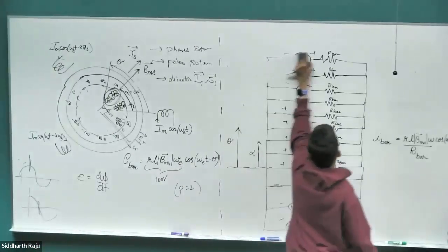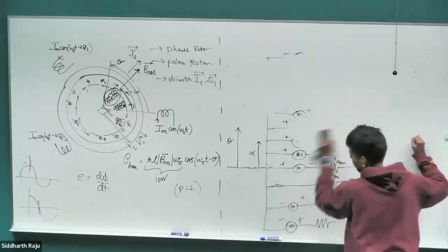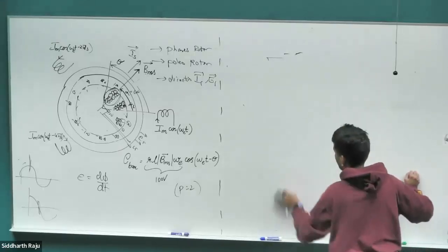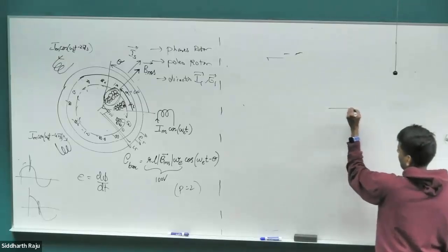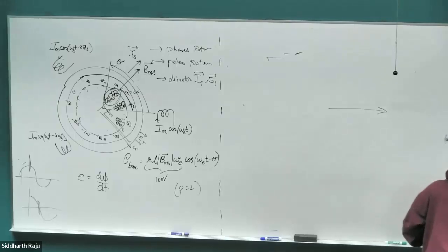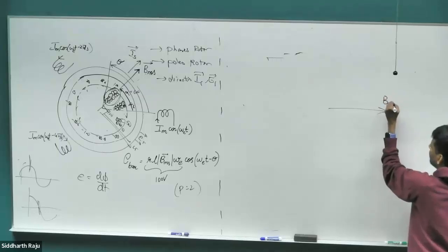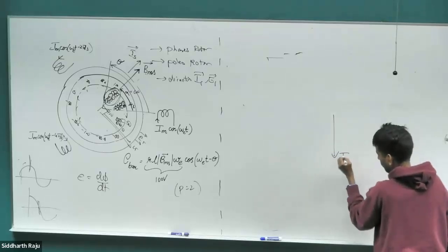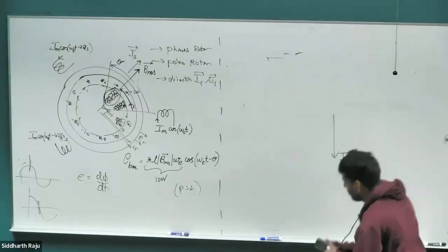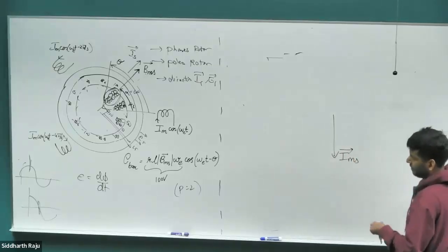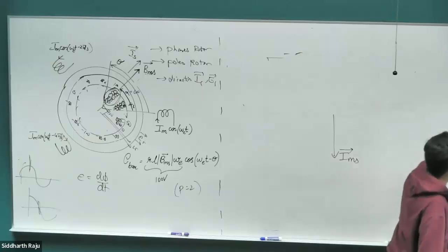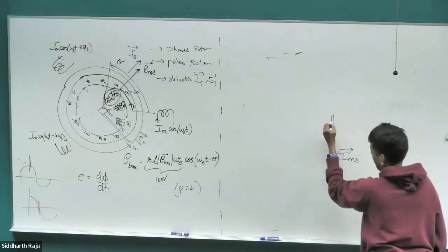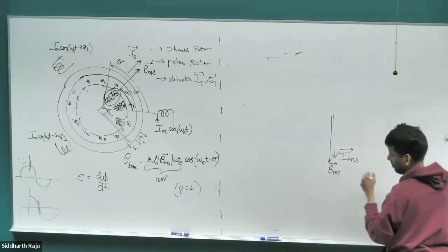So let's come back to our induction motor. So let's put all the pieces of the puzzle together. So on the induction motor we'll start off with our, this is the same convention the book is using. So the currents, the EMF phase vectors are along this direction. So this is the stator current, basically the current flowing into our equivalent model that we have for our stator magnetizing inductance. And the EMF phase vector is going to be along the same direction.